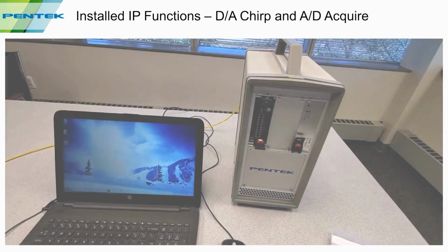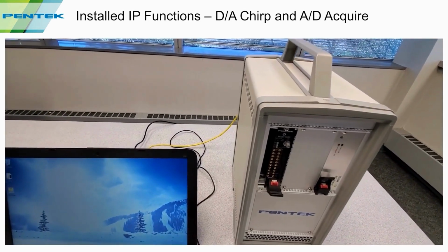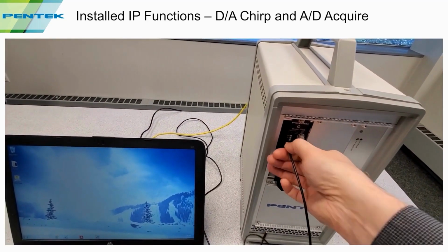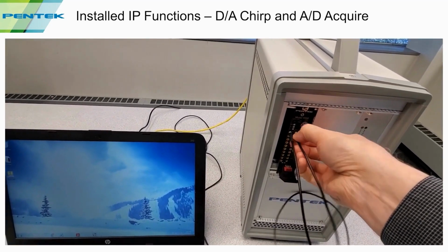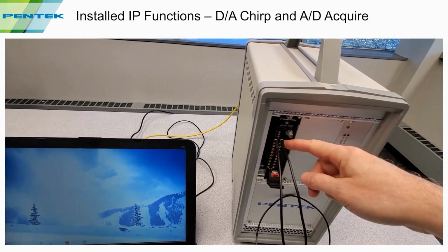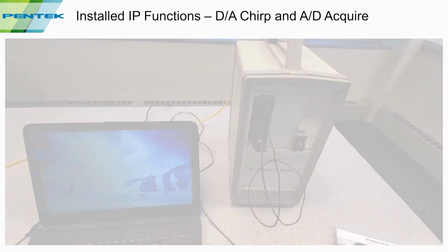We need to send the output from one DAC channel into the input of another A to D channel. So I just have this loopback cable. I'll plug it into channel 1's DAC output. It could be any channel, I just chose one. And then we'll plug the other end into the A to D input. And that way now we're sending the DAC output from channel 1 back into the A to D input of channel 1. Let's take a look at the software.